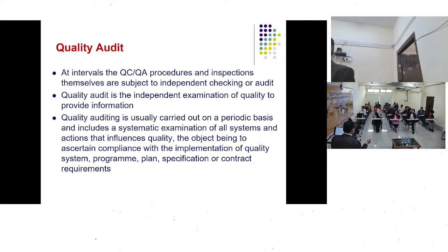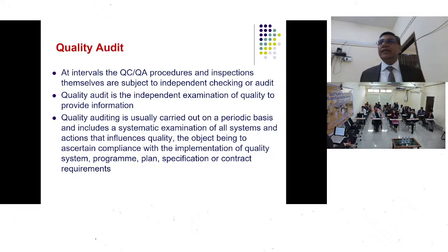So what is the weight per square meter or per square feet of that particular material? Now, can weight qualify the mechanical properties? No. If we talk about geotextile, the tensile strength or the permeability of that cloth cannot be defined in any way with the mass per unit area.